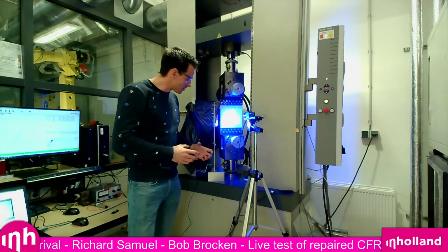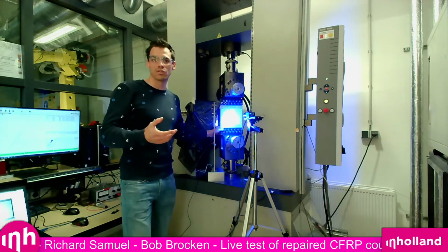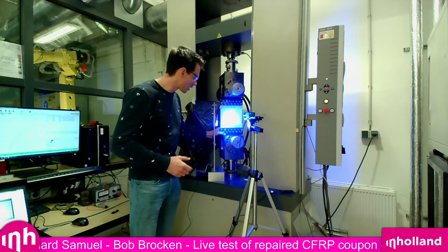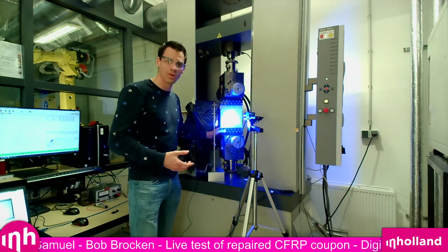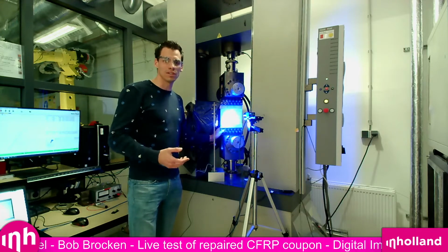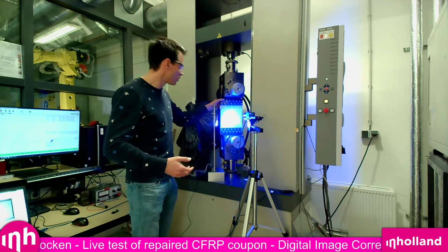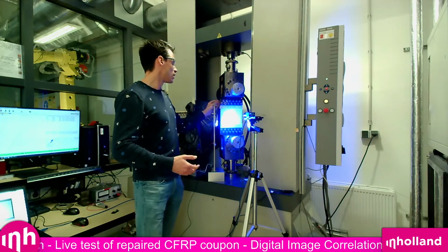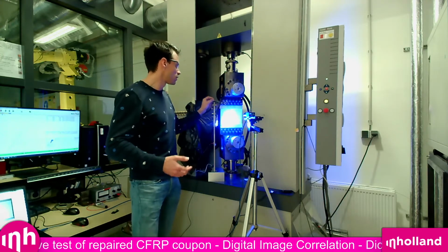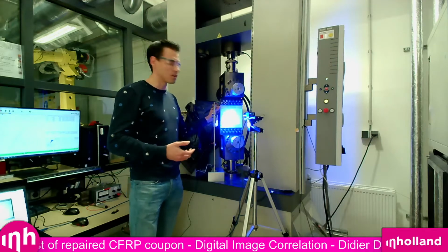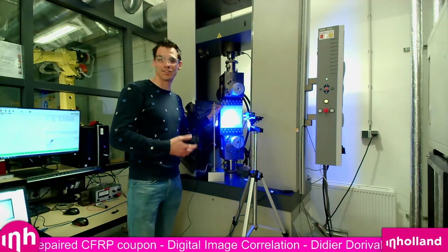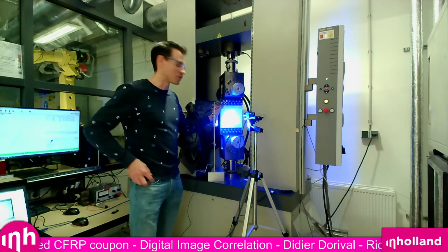Since the clamps only have a diameter of about 70 millimeters, and we're clamping a 200 millimeter wide sample, you get a very large stress concentration around the area of clamping. So what we've done is we use these steel clamps, which are bolted through an aluminium plate, which is attached using glue on the composite plate.